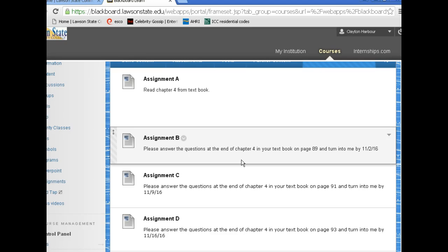That's kind of a big word. And so a lot of times they will abbreviate it with L1 and L2, which means line 1 and line 2 for pole 1 and 2, and T1 and T2. T1's across from L1, and it signifies load. Okay?